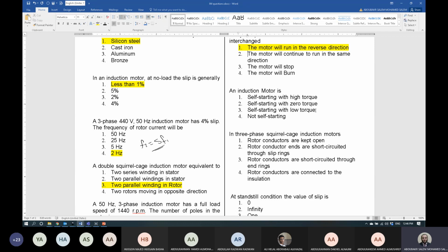Right or wrong? In a DC series motor the maximum torque will be at starting. However, the case here is not like the DC series motor, but for one of the classes, class D induction machine, the starting torque equals the maximum torque.